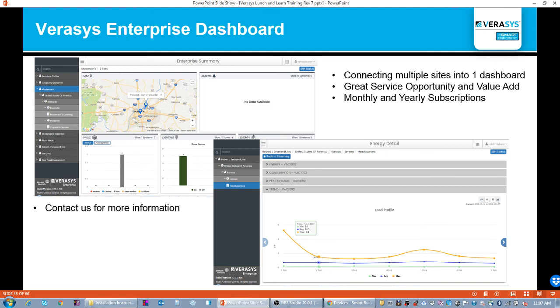So a lot of neat little diagnostics that we have that are above and beyond the Smart Building Hub. Basically, what you can do for data. Note that the trends we have on devices inside the controller are about 200 points to be able to trend, or kept 200 samples, and then it overwrites each other. There's no long-term storage in the Smart Building Hub. Our long-term storage is done through the dashboard. So that's how you can get trends that are longer than what we currently have.